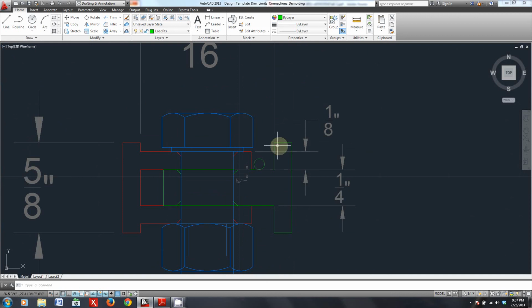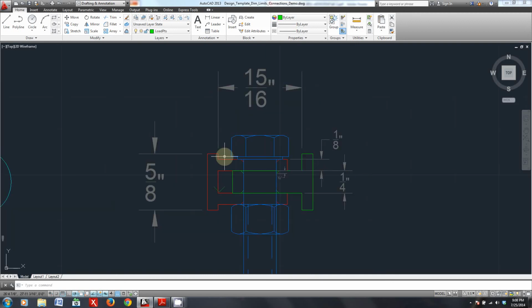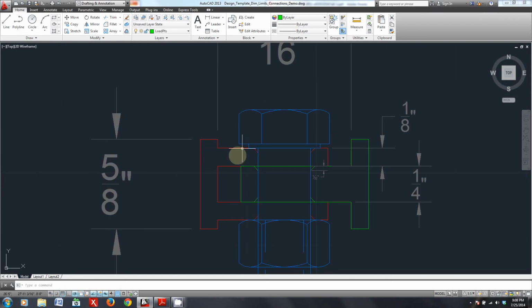Now, as for the lip width, this would be your personal preference, but I would suggest maybe even conducting some tests for welding purposes. You want to have a thick enough base such that when you weld this base onto a tube, you're not going to be warping your connection. That's especially dangerous if you're considering welding on a female connection. Because if you welded here and here, say, and the base plate was really thin, then both of these female wings could really easily start bending around, and that's not what you want. So you want a thick enough base to prevent bending, to isolate the rest of the connection from the welds, and to have enough material to actually weld on.